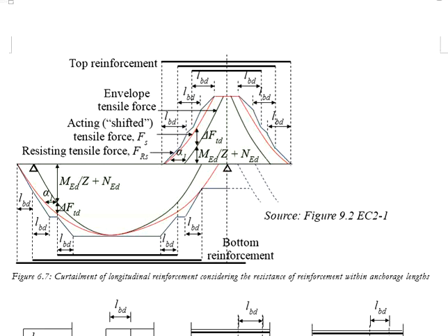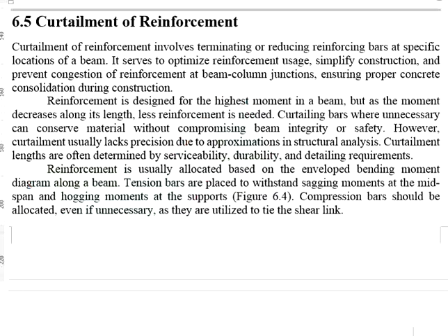In this case, you provide the 2H12 reinforcement of 12 mm diameter throughout the beam. That's why previously we mentioned the final detailing might not be fully governed by the curtailment that you have calculated. There are also other factors influencing the final detailing of the reinforcement.